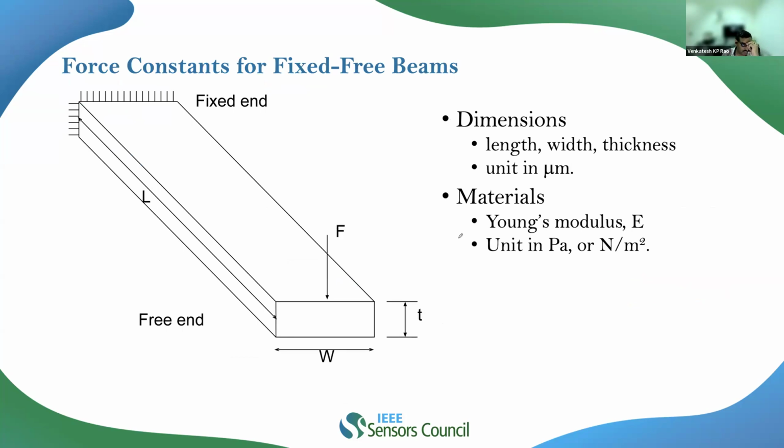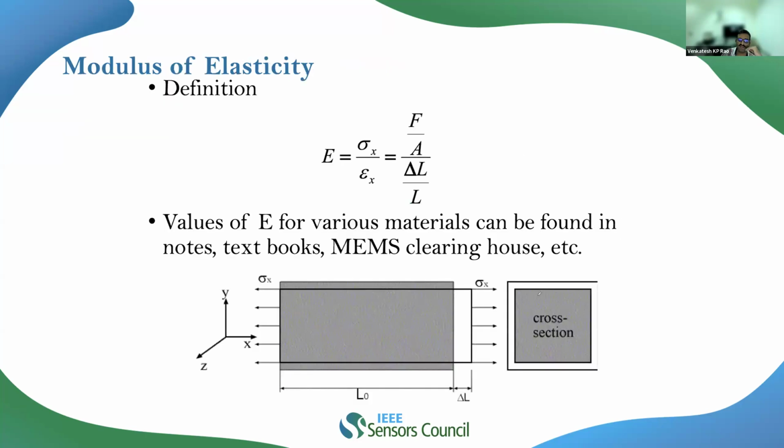Now, for example, what would be a typical force constant of a fixed free beam? So you know that if I apply a load, for a simple cantilever, it will be 3EI by L cube. So if you know the dimensions and the material properties, you can evaluate.